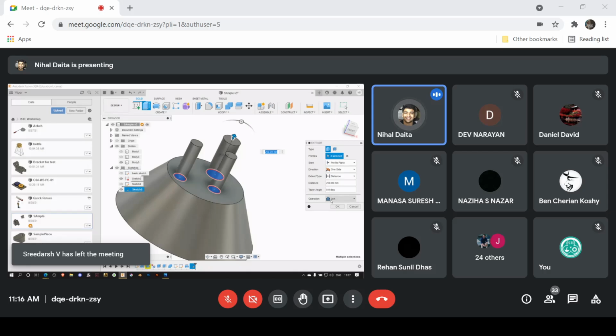So I think I have not mentioned earlier either. Since this is a new sketch and this is a new body being created, or it's a new feature being created, right? There are options to either add it to the existing geometry in contact, or you could create it as a separate entity. So if you look here, there's an operation called join, right? I think this should be the default one if you're trying to create more geometry, right? If you're trying to separate it, there's this new body option. And if I click OK,